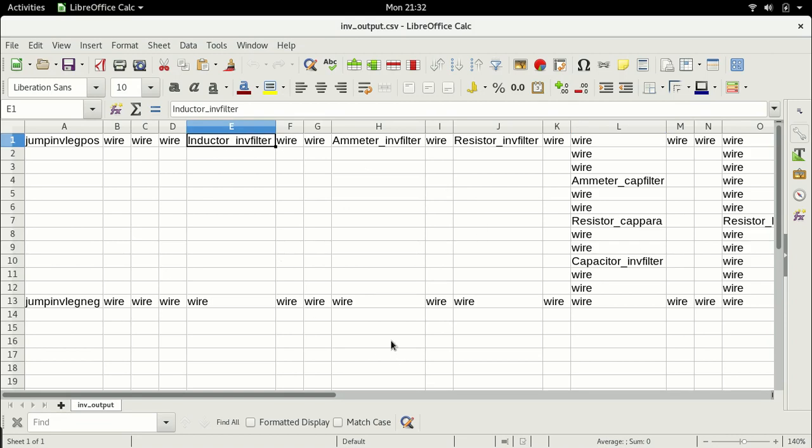So if this is our inductor, then 1 by square root LC, this is the resonant frequency. Alright, now this is a very important number, for the reason is simple. By changing inductor and changing capacitor, you can change the resonant frequency, and therefore you can change the frequency at which you begin to attenuate the output. Alright, so I'm just going to remove this.